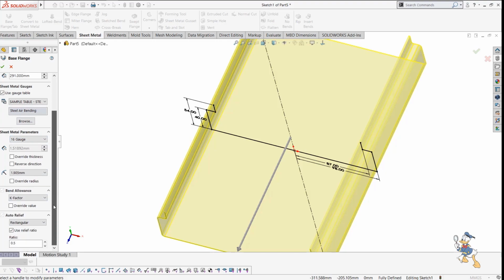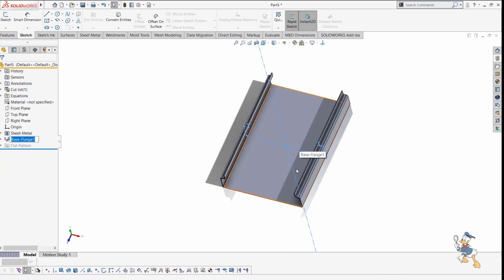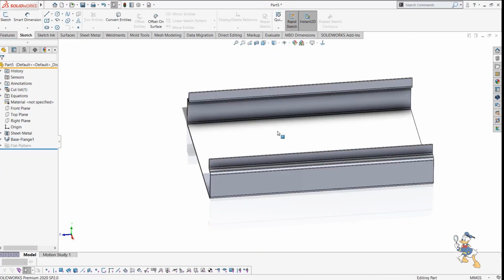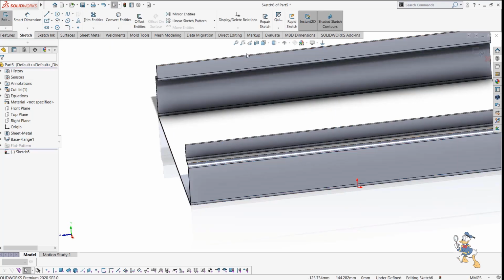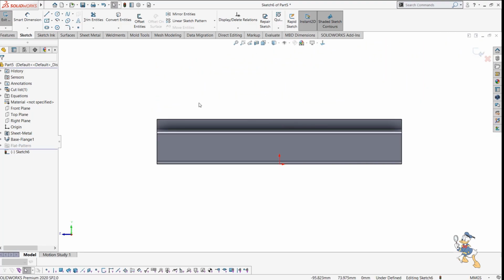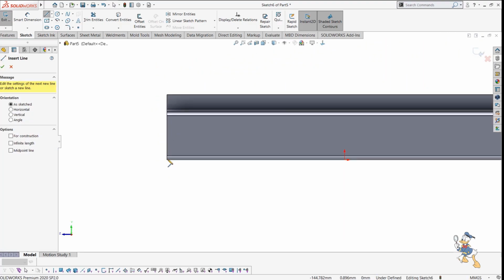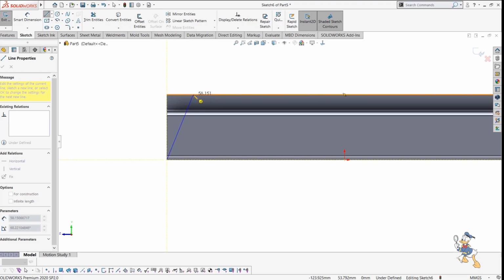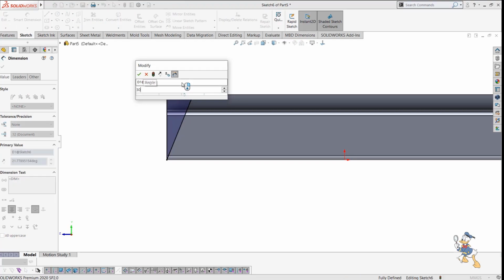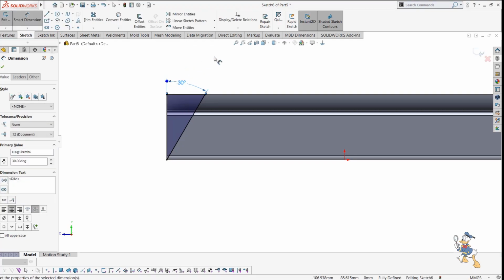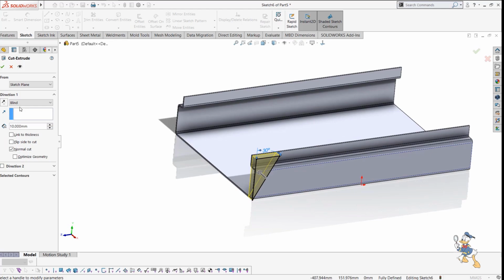Right now everything is predefined for other stuff, so I just need to check it out. So now the sheet metal component blank feature is ready. This is the basic feature which you need to start with for the sheet metal component, the blank command. Here we could also design bending as well, but right now we don't need to design a bend because in the sketch itself we have done some bending. So Solidworks is a smart software which does many of the work on that basis.